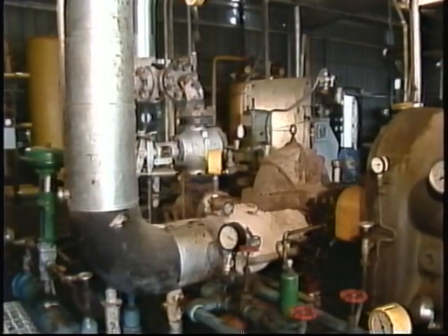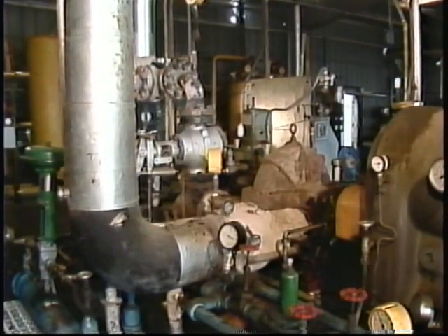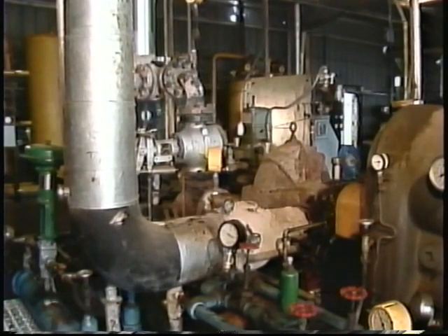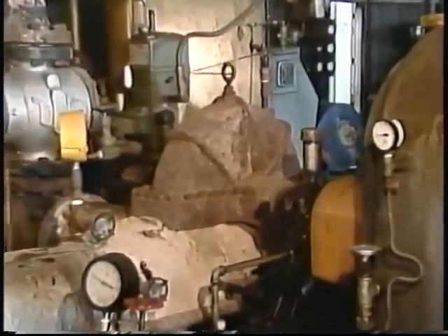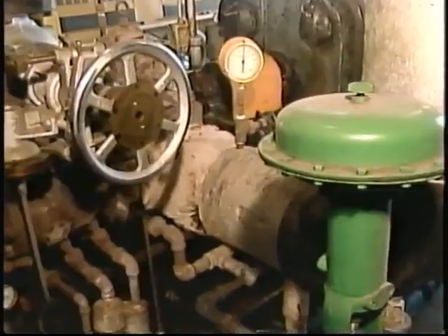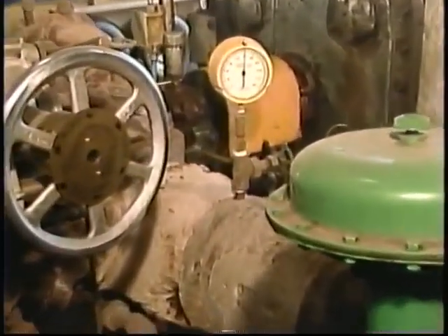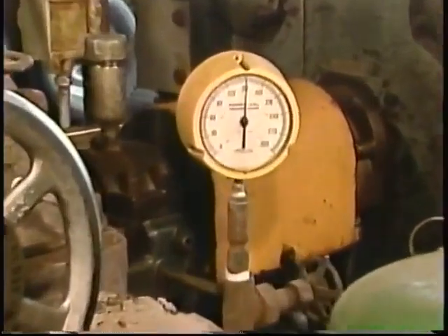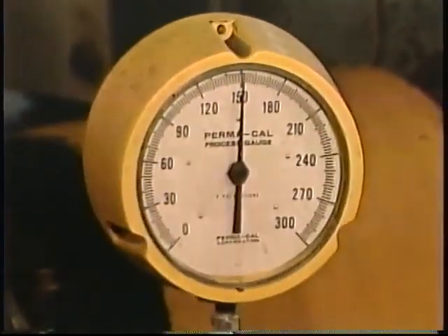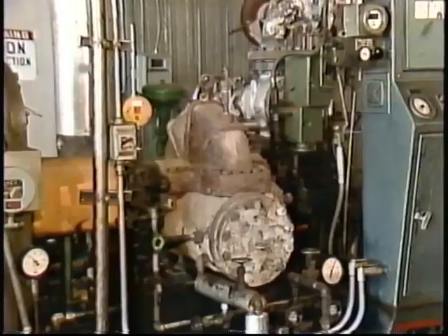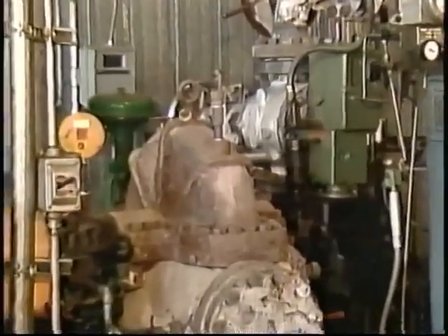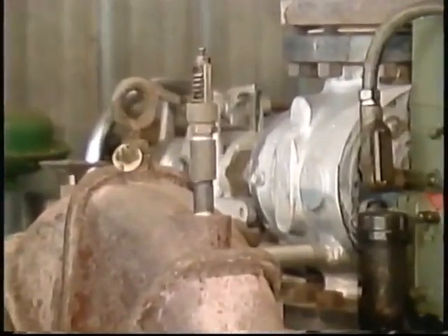A steam turbine relies on the maximum pressure difference between high inlet and low exhaust pressures to do the best or most efficient job of producing rotary mechanical energy. Excessive exhaust pressure is usually a sign that the turbine or the steam system it discharges to is not operating as efficiently as it should. Also during operation, pressure can build up in the casing.